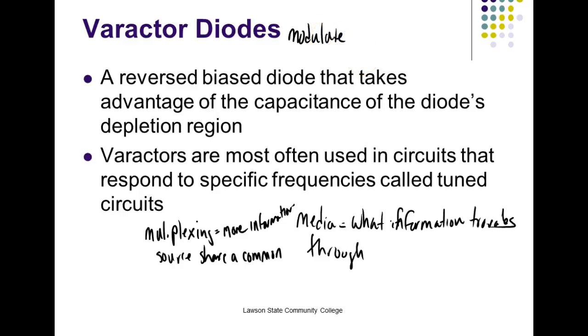We probably use this term often, but modulate means we take the information we're trying to send and then we place it on a high frequency carrier. And then we send it out. And in that way, we can take all these signals and composite them together, and then we send them over the same medium. So you see this on your radio in your car. When you select, we call it a tuner, you've looked on the right hand side, it says MH, when you say 93.7, you look over here, it says this somewhere.